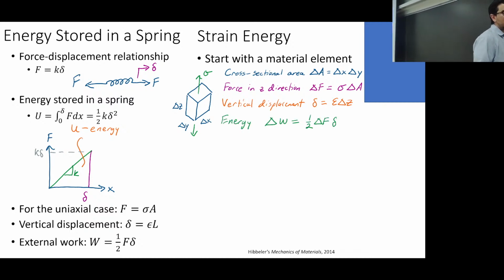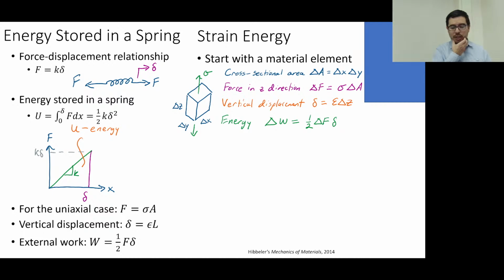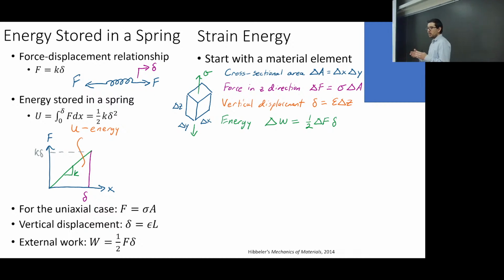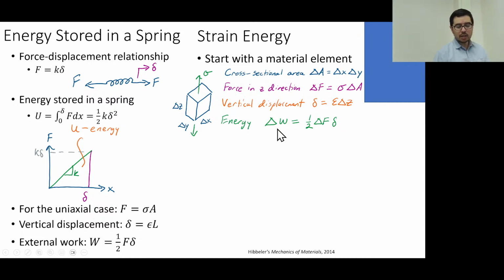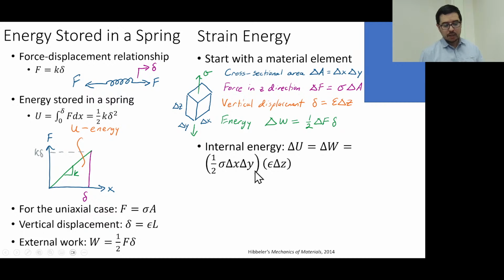And so then if we begin to think about energy, or the change in energy, right? And we think, oh yeah, we had this 1/2 force times displacement over here. Okay, what I've done here is I've said this is actually just a chunk of material. This is actually just a spring, but we have really small dimensions on it with really small forces. Okay. And so we can say, oh, energy is energy. So the change in the energy here is going to be the same equation that we had over here. Okay, so now we can talk about this internal energy.